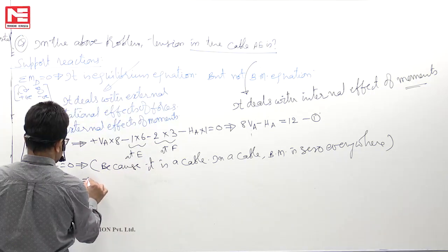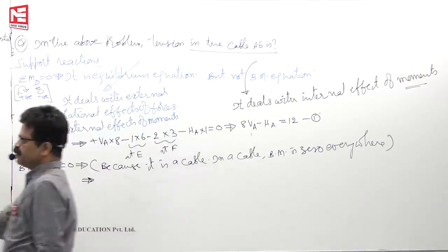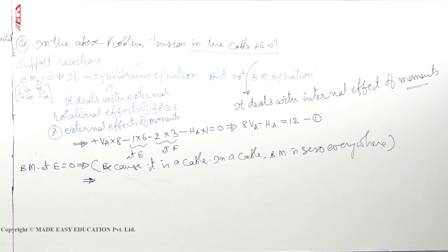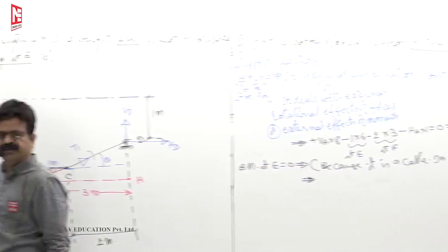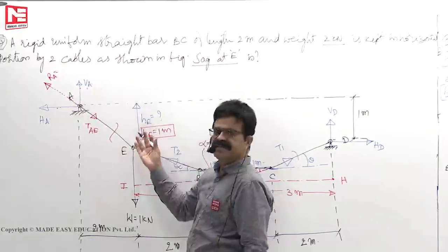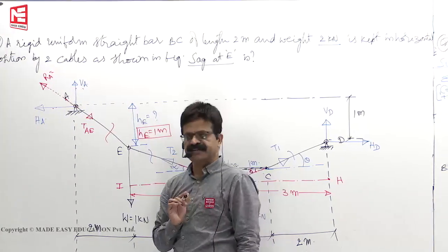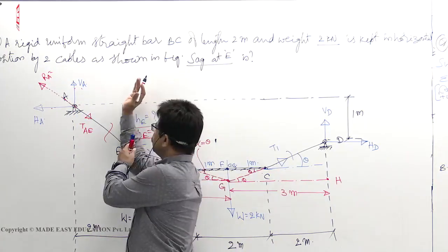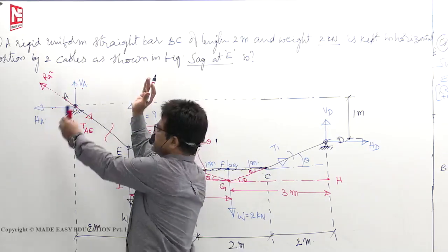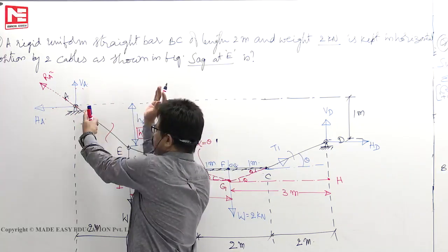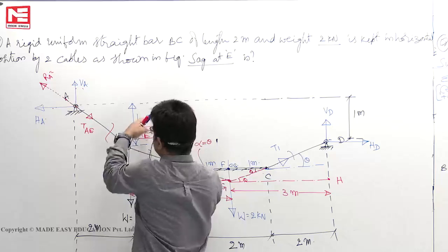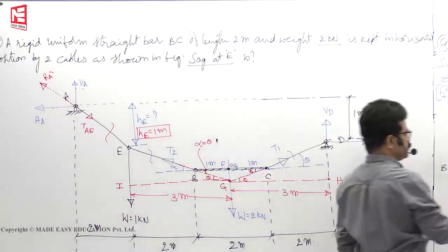That's why. So, to find bending moment at E, what do you have to do? We have to stand there and look one side, either left side or right side, our choice. Whatever side you see, you will get the same result. Stand at E, look left. How many forces are there? VA, HA. VA into 2, HA into 1 must be 0.